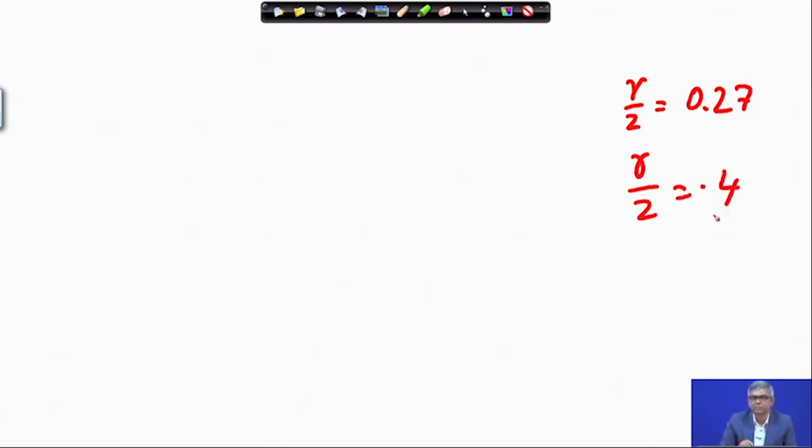If I fix the depth equal to z, 2 meter, then r will be some value, suppose r1. That means, if the circular load area has radius r1, and that much area is loaded with intensity q, at 2 meter depth your intensity will be 0.1 q.